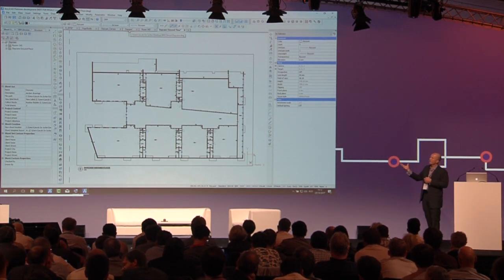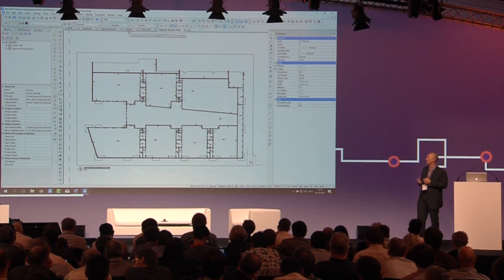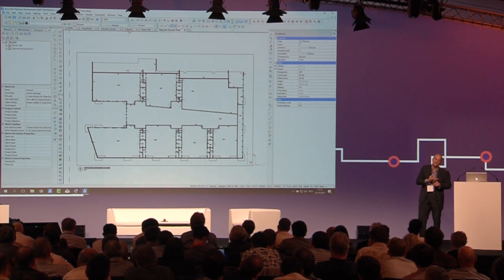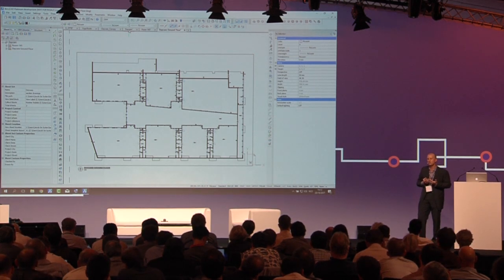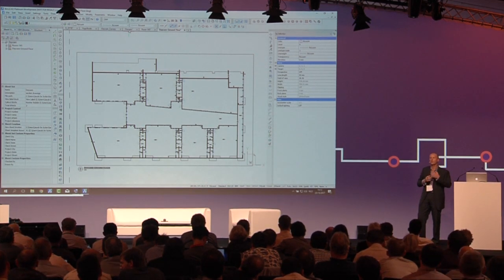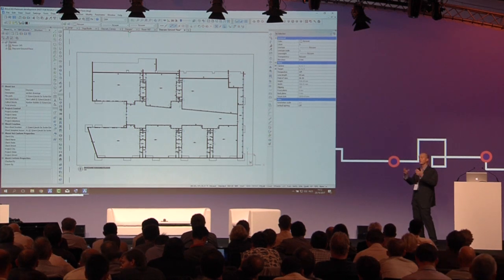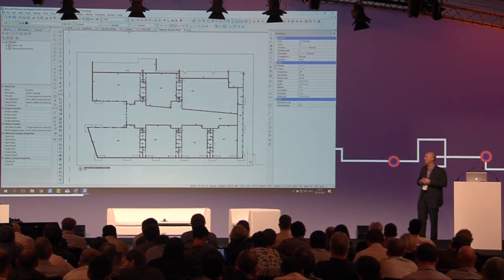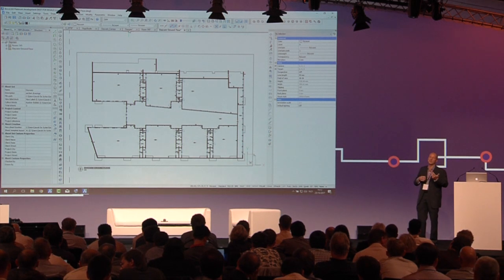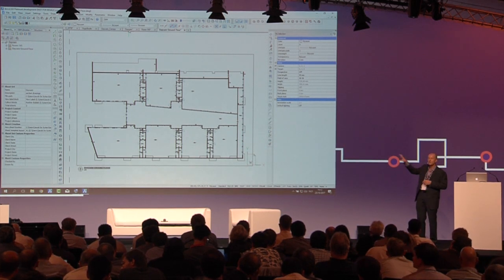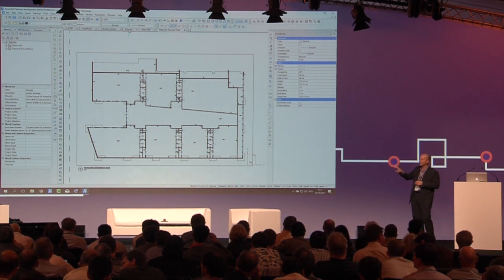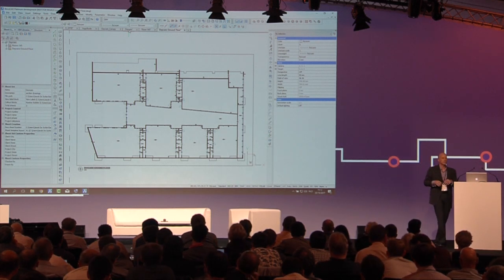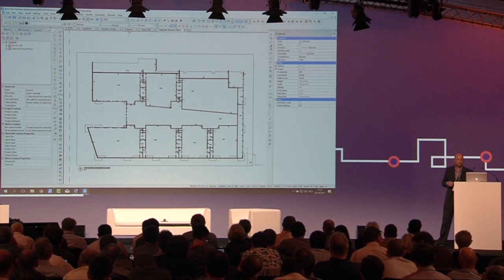So, a quick example in terms of BIM tags, but if you think about BIM tags and interior elevations, think about the time savings that are potentially possible on a sheet, on a project, on a large development project. There can be quite a number of time savings in terms of not having to go back and update the tags based on design changes, and that they're linked to the information that you're incorporating into the BIM and the models.